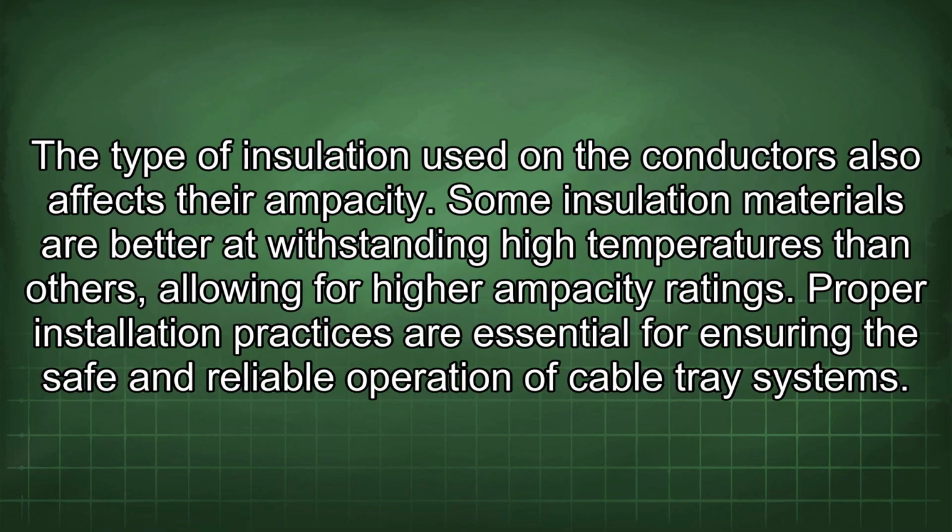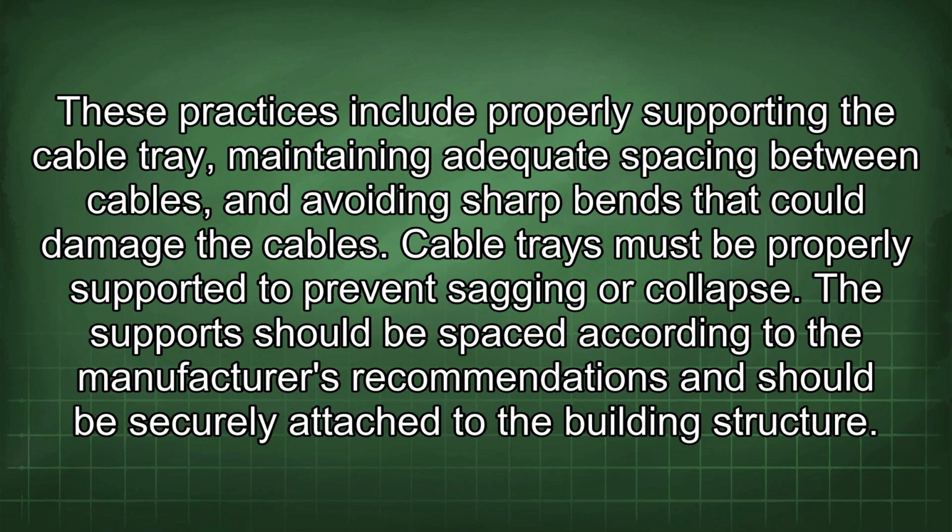Proper installation practices are essential for ensuring the safe and reliable operation of cable tray systems. These practices include properly supporting the cable tray, maintaining adequate spacing between cables, and avoiding sharp bends that could damage the cables. Cable trays must be properly supported to prevent sagging or collapse.